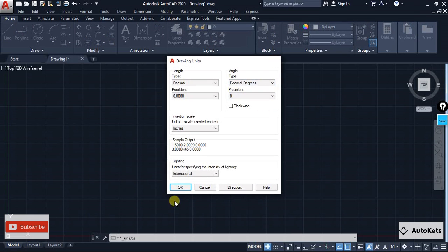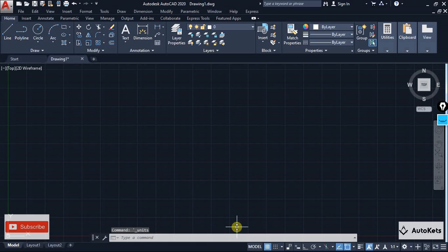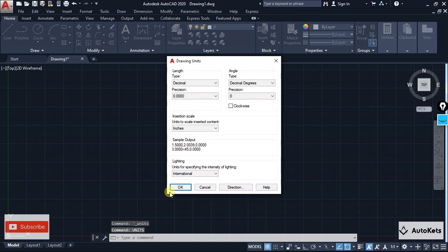The third and the very quick approach is to just type unit in the command box. The command box, as I have told you, is a very important thing, and whatever command you type over here will be available without searching in the toolbars. So let's say that we want unit, so I'm going to type unit over here, and you can see that it shows you a unit list. Just click on that or just press the enter button. You can see that we are inside the units.